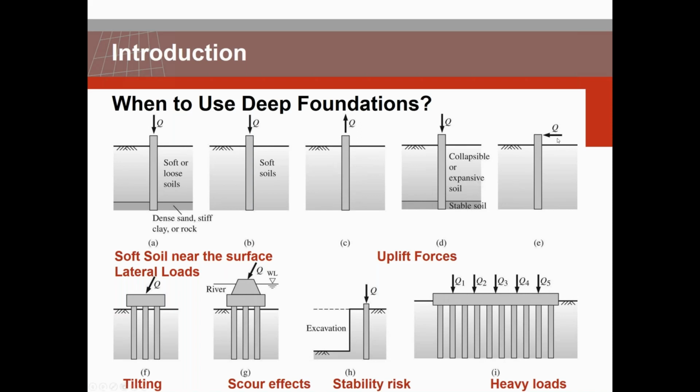If you have large lateral loads that you need to carry by your foundation, if you have tilting or scour risk, like foundations for bridges in waterways, stability risk, foundations near excavations or slopes, or if you have heavy loads that cannot be carried by traditional shallow foundations, for instance.